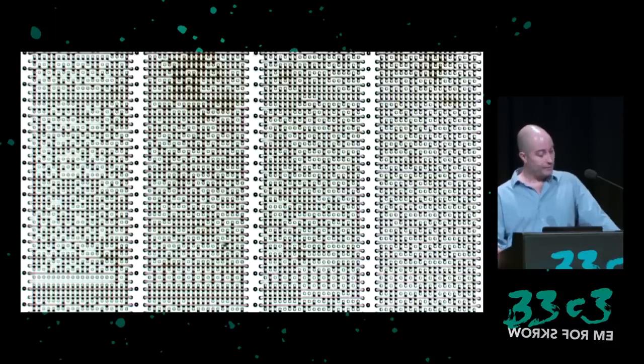With the visible bits exposed and photographs taken, the bits can be extracted using a software image analysis tool, or the bits could be extracted manually. The ROM here is 32 kilobytes, or over 260,000 bits. So manual extraction would be a bit labor intensive, but it isn't impossible. A software tool is more efficient.